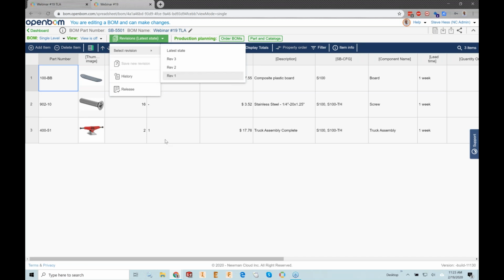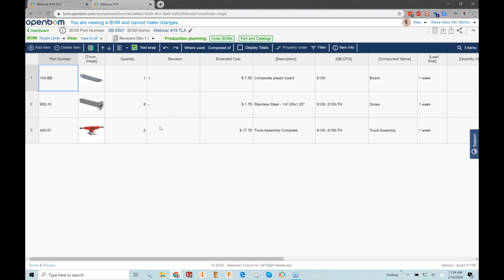So use this type of process of changing those revisions of those sub-level bills of material, creating an upper level bill of material, an upper level revision for the top level bill of material, and creating that as read only. And if you're using a BOM tool, of course it will do it automatically for you. If you're using Excel, you just save that thing out and put it in a directory that's read only, or set it to read only. And you'll end up with a history of revisions that you can work your way back through and see.